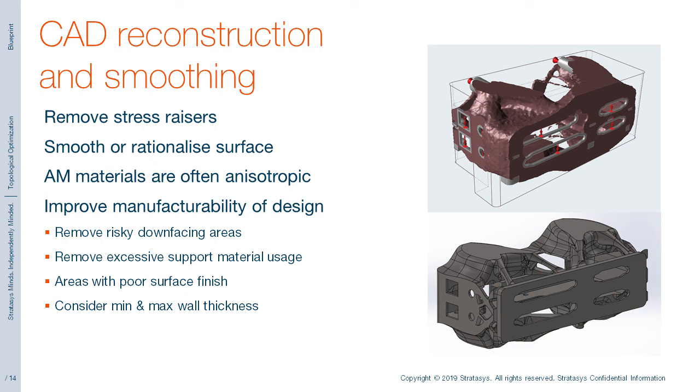Its shape might make it difficult to hold, or it might be prone to collecting dirt, grease and grime inside of its complicated structure. In this CAD reconstruction and smoothing step, we can add back in the human designer. We can redraw the results of the top-op simulation into a more logical design and smooth out those lumps and bumps caused by that coarse mesh.